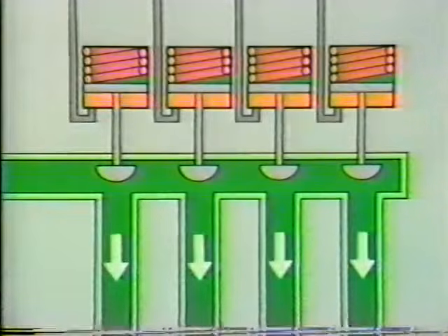The control valves are operated by hydraulic actuators. These valves regulate steam flow to the turbine by opening and closing in sequence. As each valve opens, more steam is admitted to the turbine. At normal turbine operation, the control valves are positioned as necessary to compensate for changes in load. At full load, all the control valves are almost completely open, allowing a full flow of steam to the HP